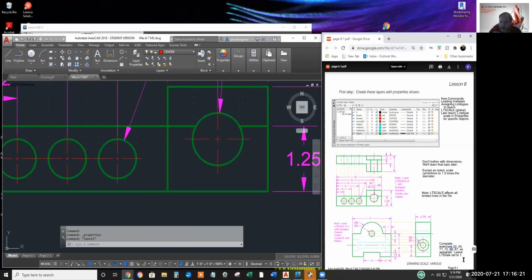Okay. How about let's put them on the same drawing, keep global LT scale as unity. You want to use just one centerline layer and change the personal property of each and every centerline accordingly? Yeah, that's fine.